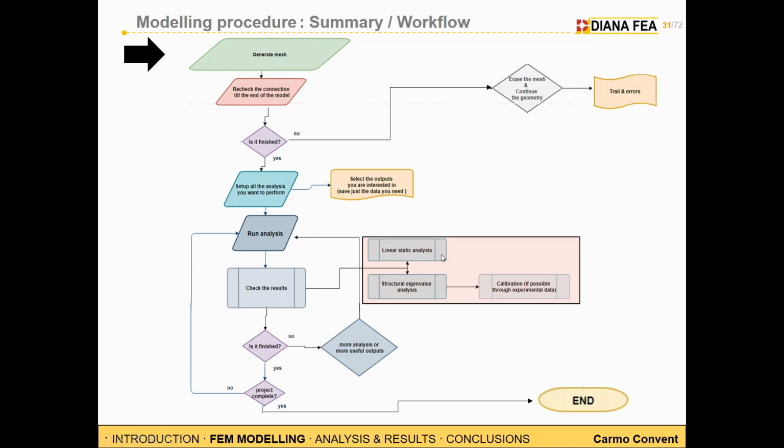The linear static analysis is powerful to understand if the units are correct, but also if the total vertical displacement or the reaction at the base of the structure are realistic or not. On the other hand, the structural eigenvalue analysis, also called modal analysis, is useful to understand the dynamic behavior of the structure and also to calibrate the model itself.